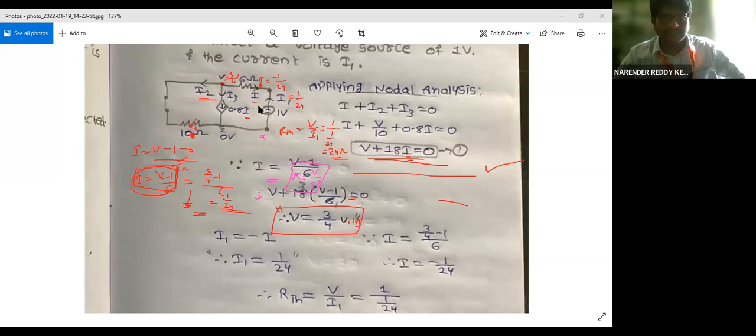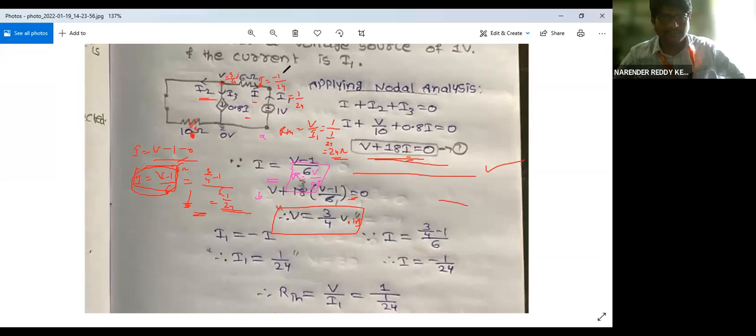So all we are doing is a reverse process. We don't know how this equivalent resistance has to be calculated. So what we are doing now is using a source and pumping the current, and we take the magnitude of voltage and current which we are pumping inside and take the ratio; that will be the equivalent across these two terminals. That's what we are doing here. We are least bothered about the rest of the parameters in the circuit when you have a dependent source. Am I clear? Now you got the value of RTH as 24, right?